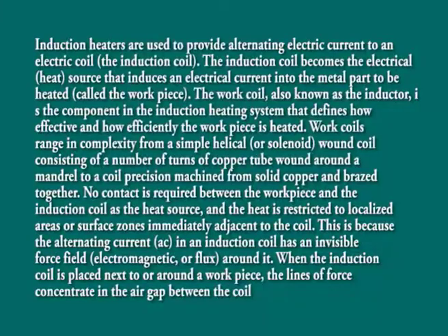A suitably dimensioned coil, placed close to the metal part to be heated and conducting high or medium frequency alternating current, induces eddy currents on the workpiece, whose intensity can be controlled and modulated. Induction heaters are used to provide alternating electric current to an electric coil that is termed the induction coil.